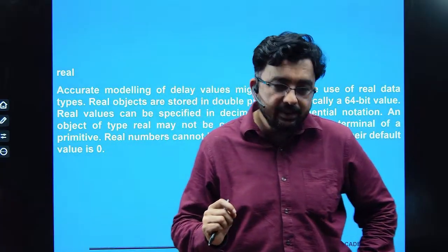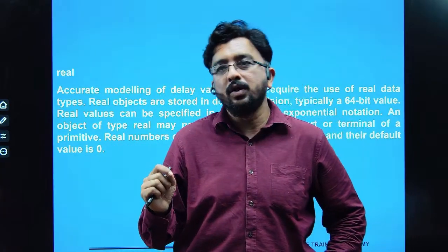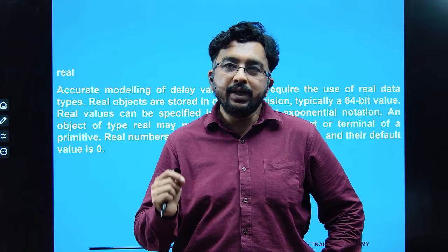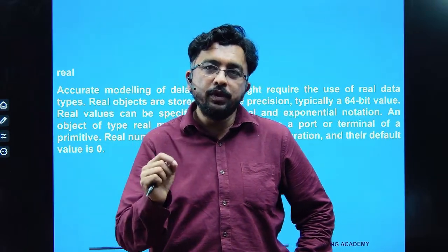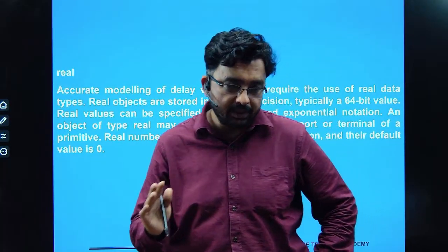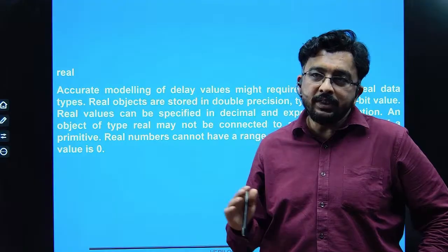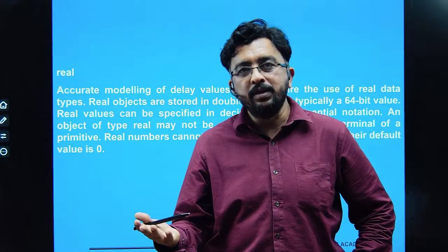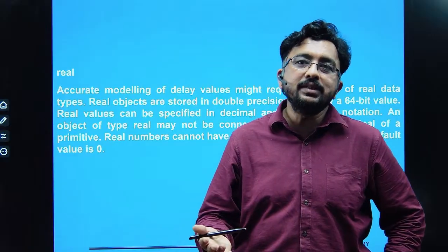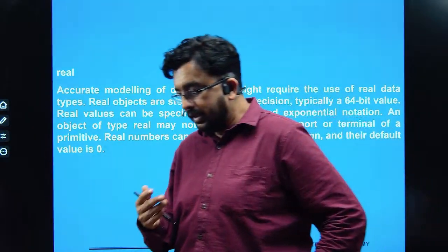Now the question is, integer is not taking care of the 4.123, and reg is not taking care of 4.123, because they both truncate the data. So what is the variable we are going to use? In that case, we are going to use real.